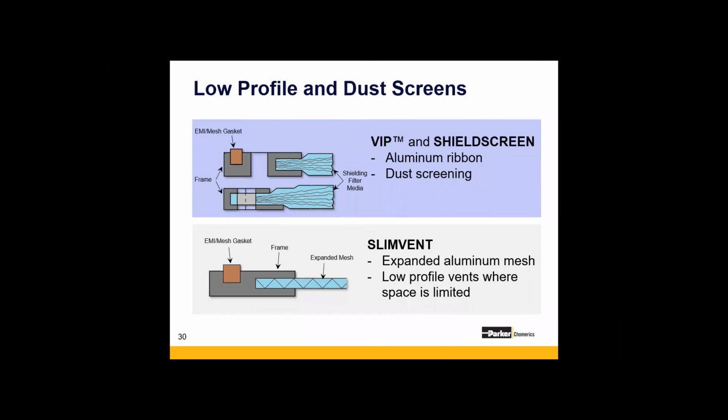So just to confirm though, the filtering medium is not a traditional honeycomb. I know we've talked about honeycomb mostly throughout the presentation, but this is a multi-layer expanded aluminum, which can be coated with viscous oil for dust impingement, and it works in applications with very low velocity airflow.